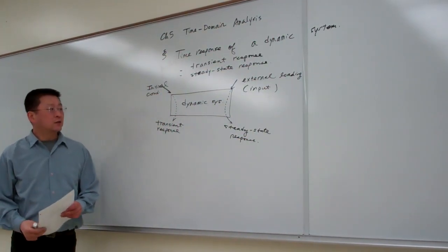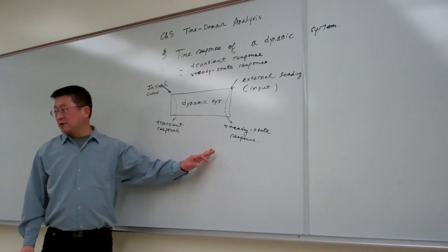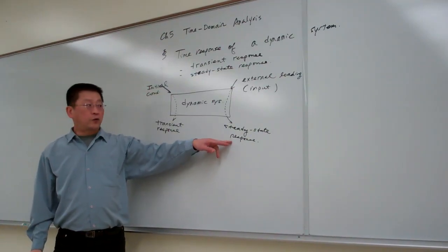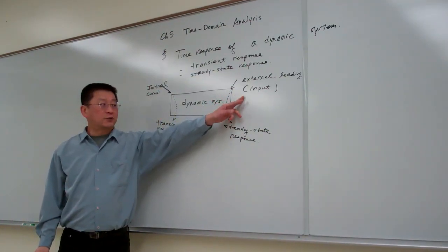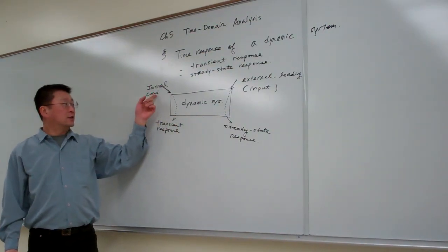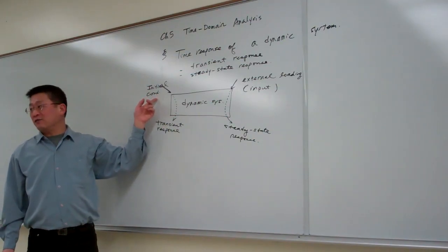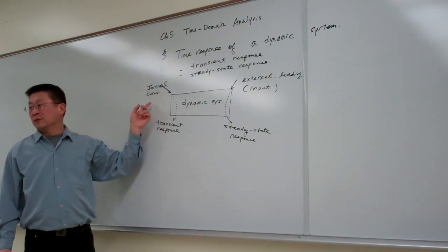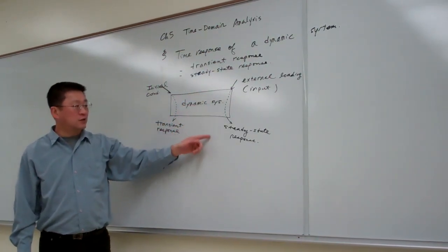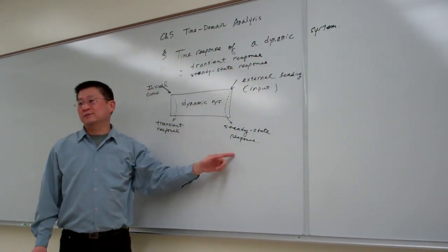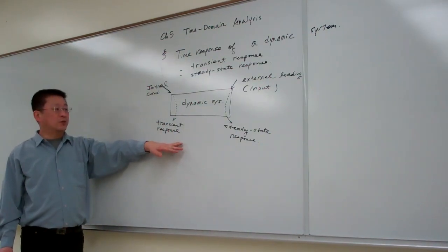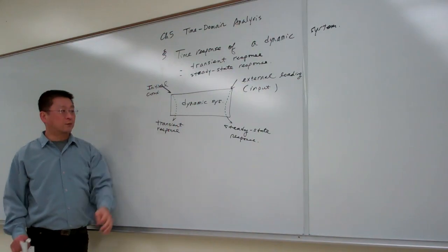In our studies, we have learned the transfer function. The transfer function is the output response as a ratio to the input in the S domain. When we study transfer functions, we ignore the initial conditions. That is the fundamental assumption, so the transfer function takes care of this part only. Hopefully this picture helps you build something mentally.